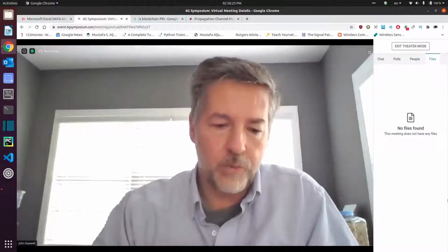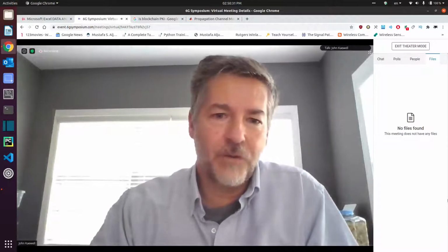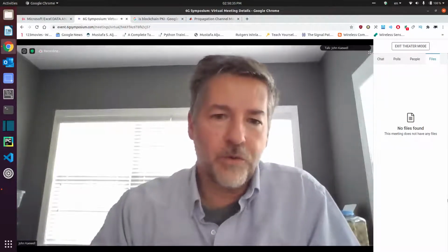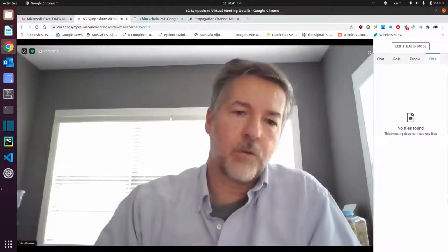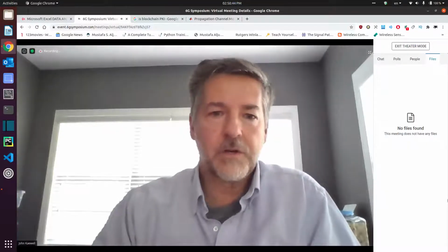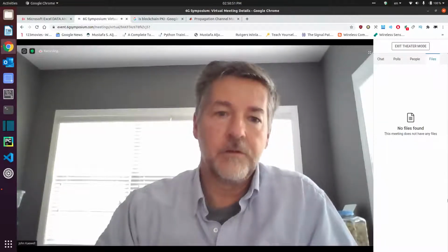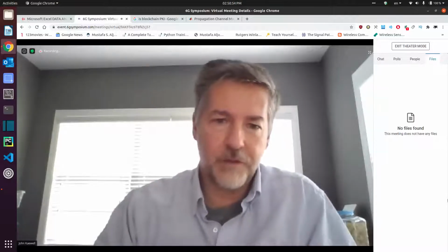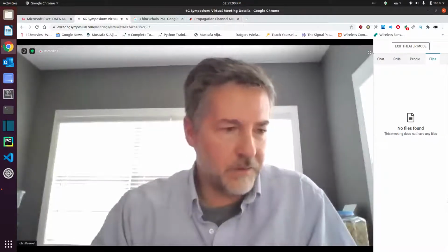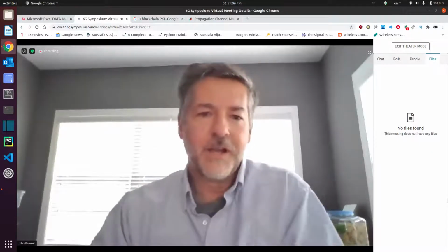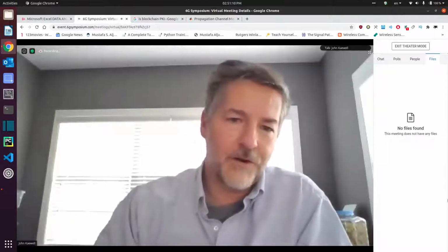And this example was done using a synthesized data set. I think the next step is to actually try it on over-the-air scenarios and try to work through, what are the steps that you have to do? How do you come up with this beamforming? The beamforming vectors were determined using a traditional approach, but then the sub 6 gigahertz uplink signal was used as the label for a particular set of those weight vectors for the beamforming. So the question is, if you've done that at time 0, does that same label still detect?